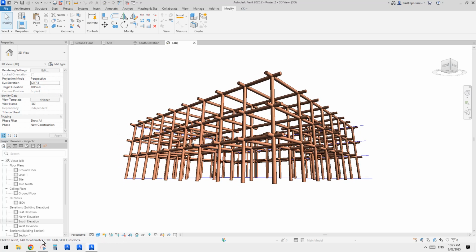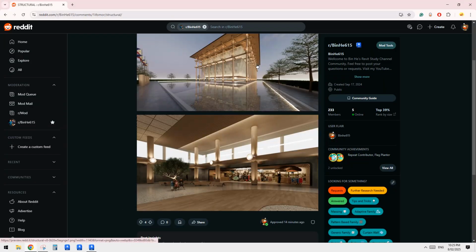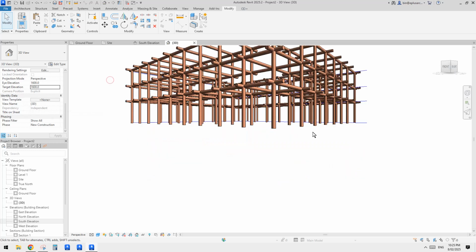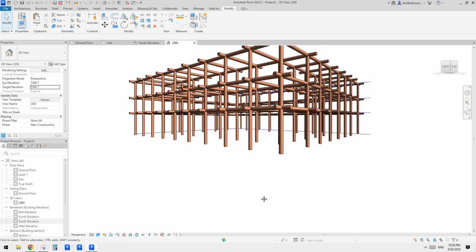If you want to do a view like this, like a perspective view, eye level view, first of course, do a perspective view, and then just make sure the eye level is roughly your height, usually 1.6, and also target level is the same, so it will create this one, right? And then, hang on, sorry, Control V again.